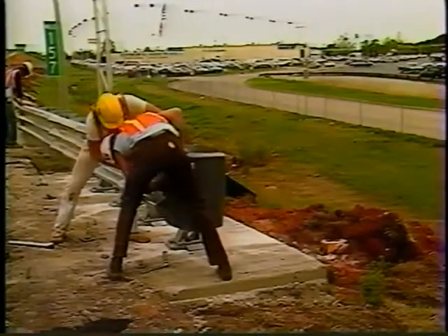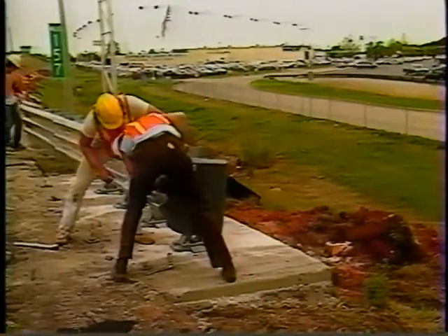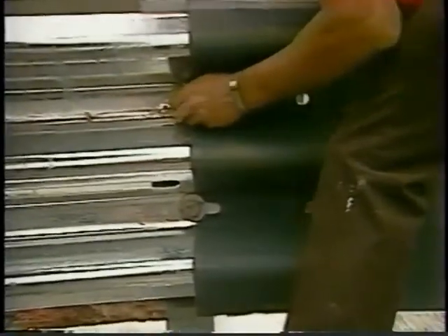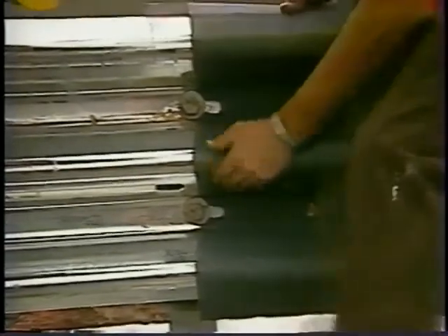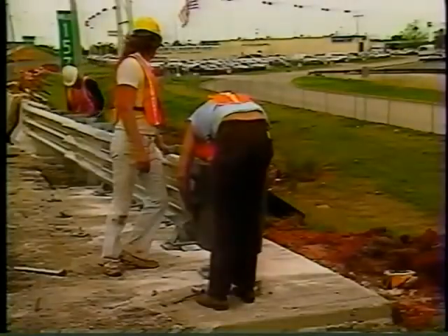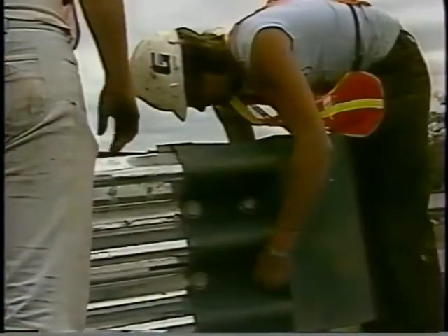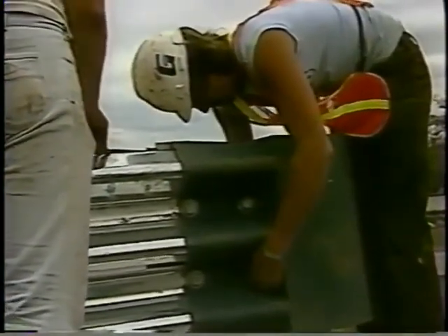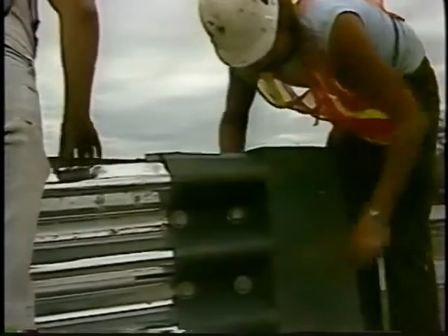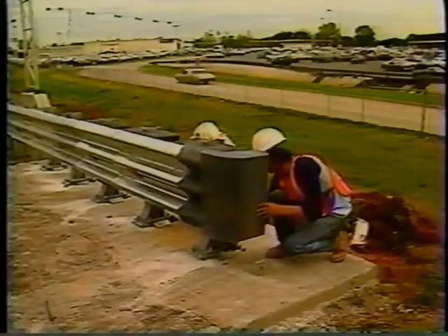The plastic bull nose is positioned over the panel but under the flat washer and bolt head before tightening the bolt assemblies. 2 bolts are also placed through the 2 remaining holes in the bull nose and through the 2 fender panel holes labeled G. The cable is now ready to be connected.